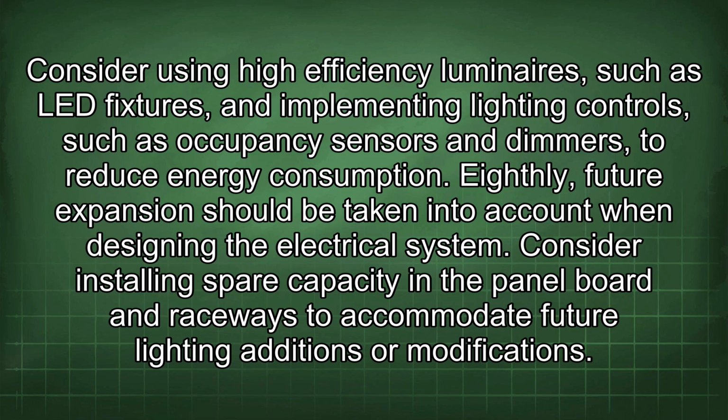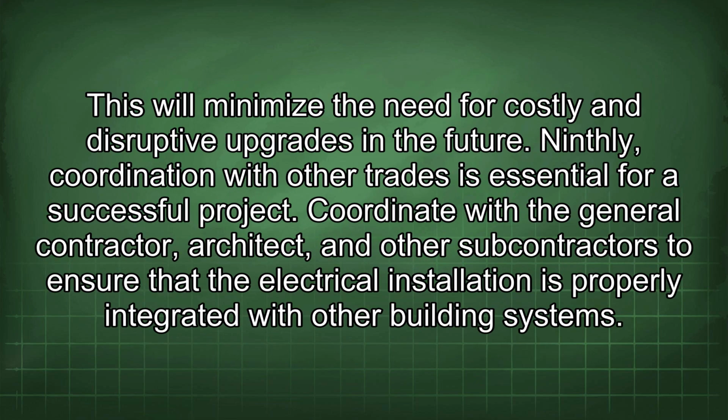Eighthly, future expansion should be taken into account when designing the electrical system. Consider installing spare capacity in the panel board and raceways to accommodate future lighting additions or modifications. This will minimize the need for costly and disruptive upgrades in the future.